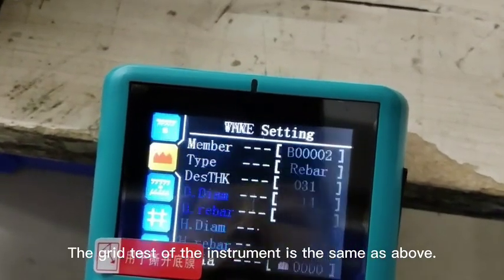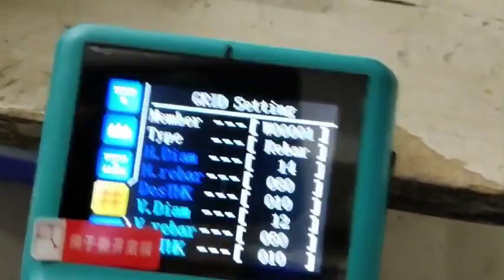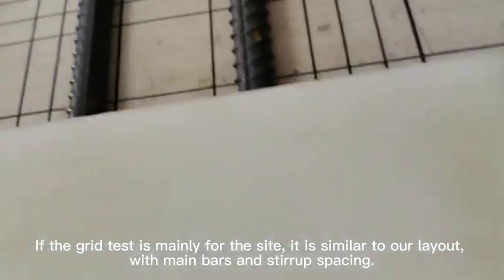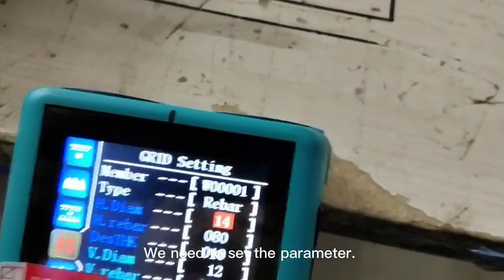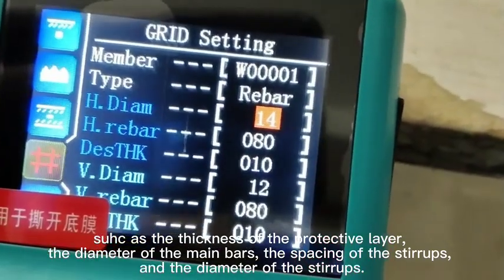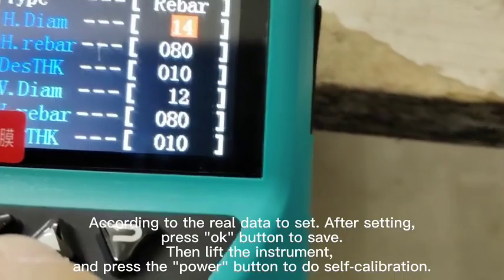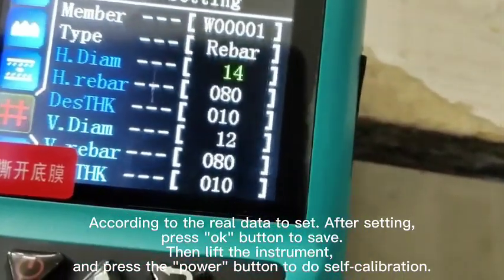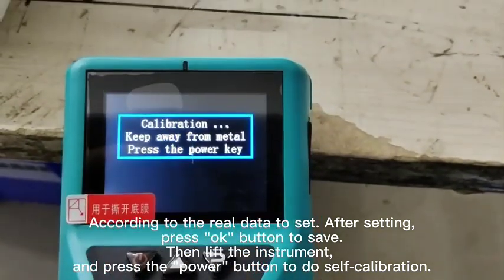The grid test of the instrument is the same as above. The grid test is mainly for the site, similar to our layout. With main bars and stirrup spacing, we need to set the parameters, such as the thickness of the protective layer, the diameter of the main bars, the spacing of the stirrups, and the diameter of the stirrups. According to the real data, set them, then press the OK button to save, then lift the instrument and press the power button to do self-calibration.